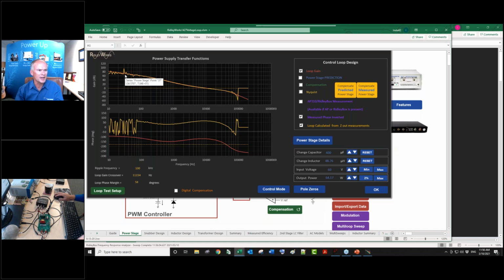But can it be done? Yeah, and everybody's known this for years. Middlebrook knew this. Output impedance is the open loop divided by one plus the loop gain. So you measure the two, you can back up into the loop gain, but he didn't suggest you do this because the loop gain is such a rugged measurement. Okay? It doesn't have this problem here.